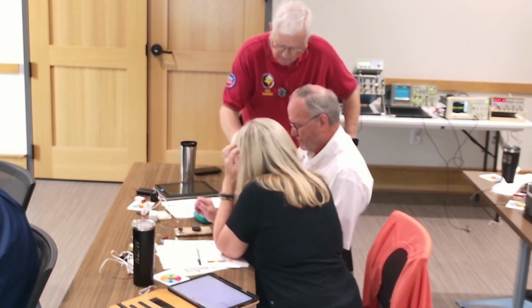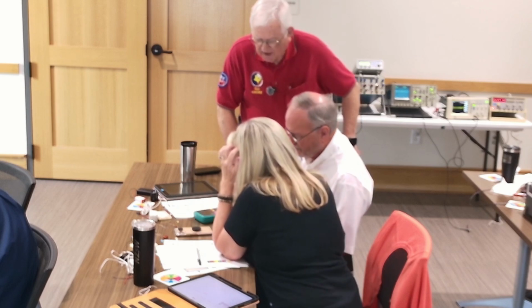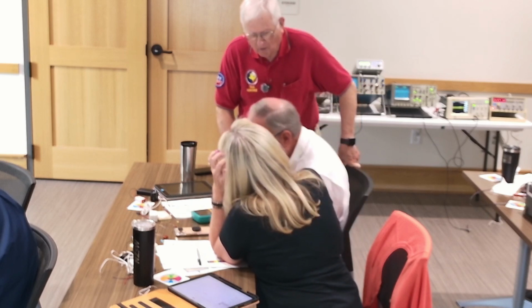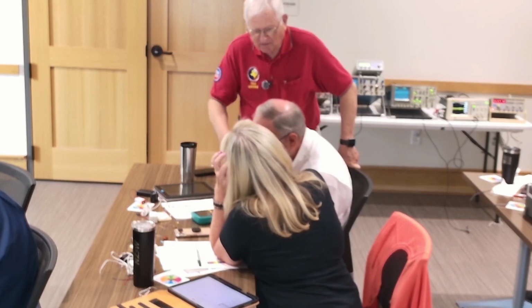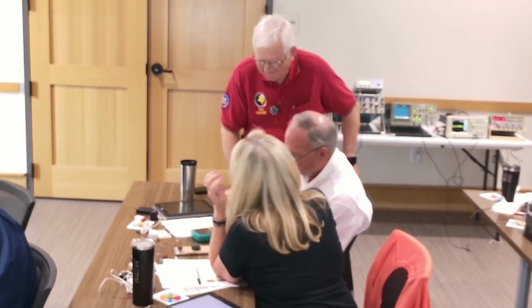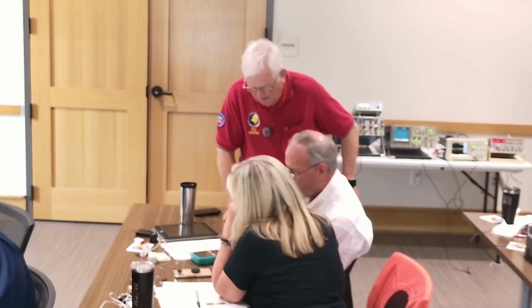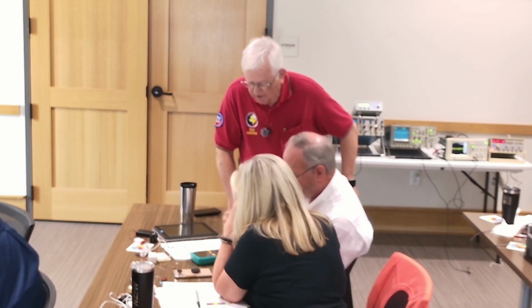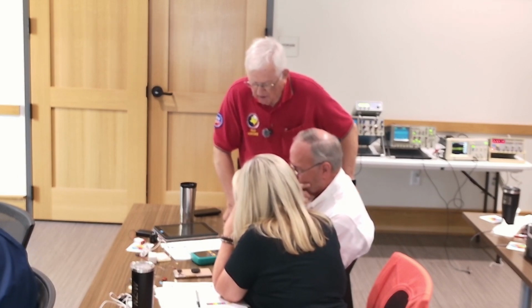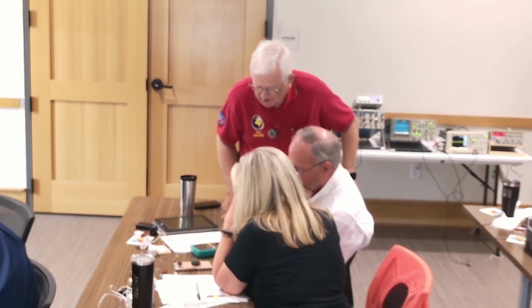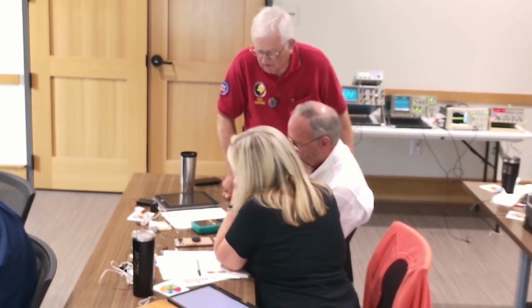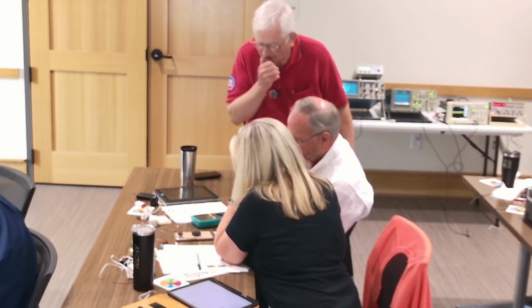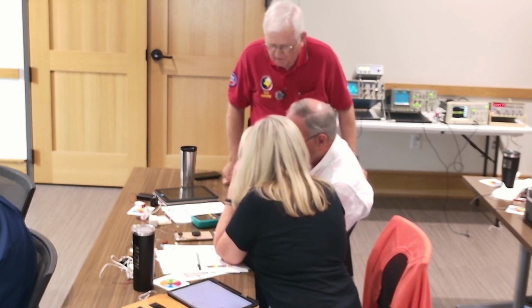And that's a 450 volt one. If we had a way that we could charge it up, we could toss it to somebody. Let's figure that out. It's 100 microfarads, and it's reading 125, which is not unusual. It could be a little high, so we come down to the next scale. There we go, 117. That's pretty close. Capacitors will vary very widely.